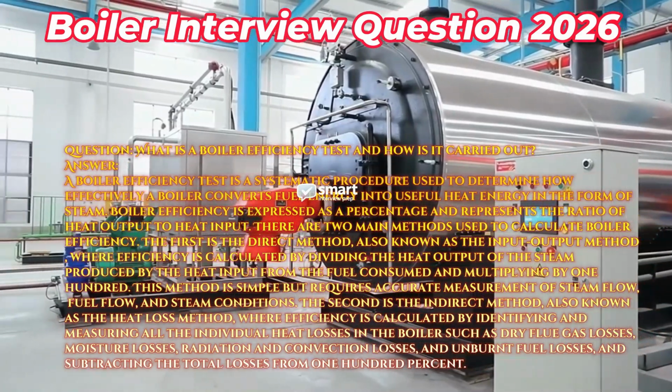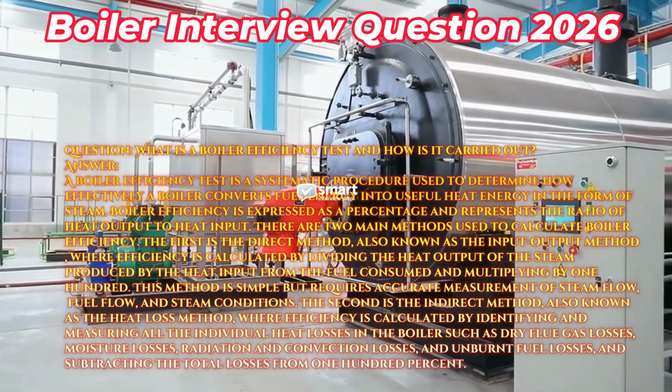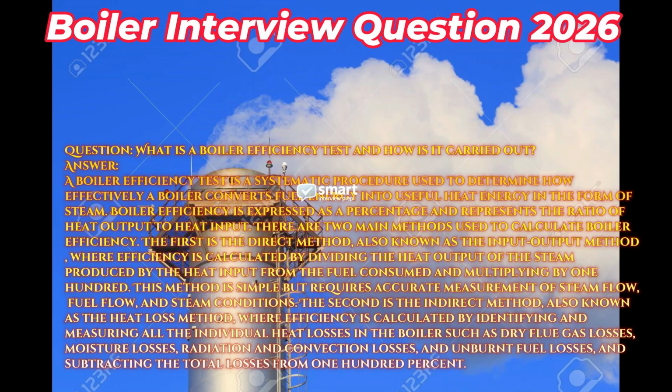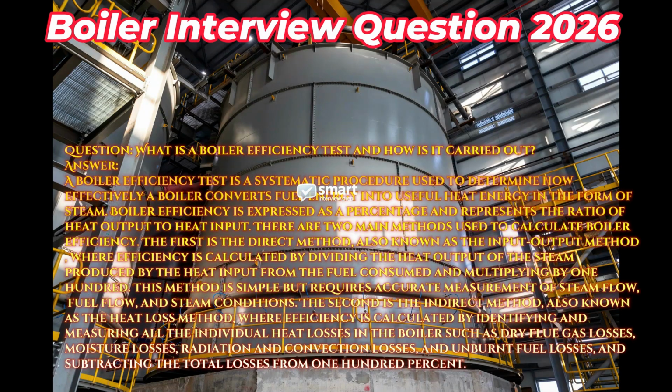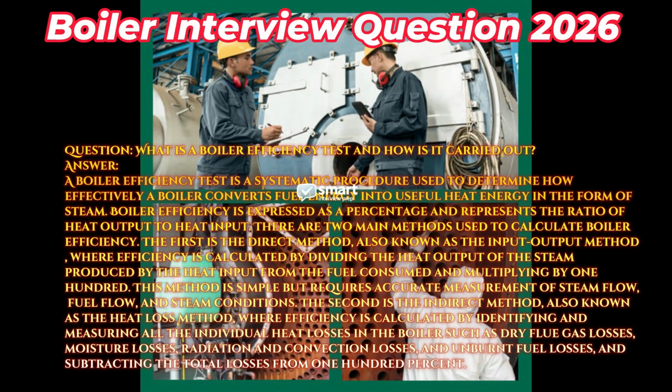Question. What is a boiler efficiency test and how is it carried out? Answer. A boiler efficiency test is a systematic procedure used to determine how effectively a boiler converts fuel energy into useful heat energy in the form of steam. Boiler efficiency is expressed as a percentage and represents the ratio of heat output to heat input. There are two main methods used to calculate boiler efficiency.